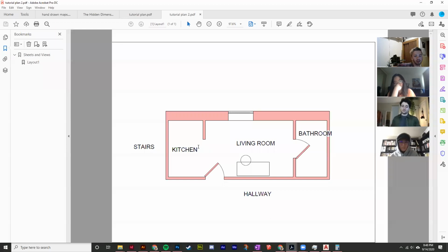So I encourage you to look at plans that you like. Notice the drawing conventions they use, like how thick the walls are, what color the hatch of the walls are, how the text is dealt with. So look around at examples, see how you want to do it. And then also remember about the framing, what I was talking about, how to represent scale. If you have a key, make sure your key is neatly organized or not distracting in that way.